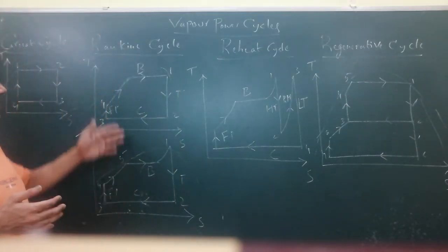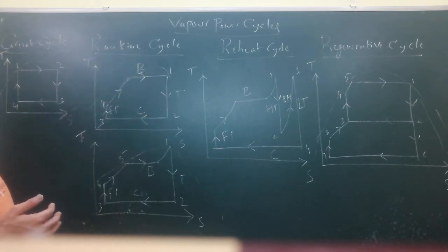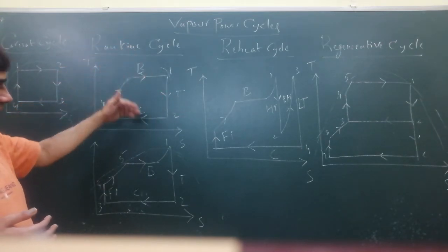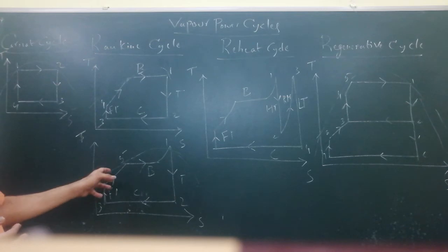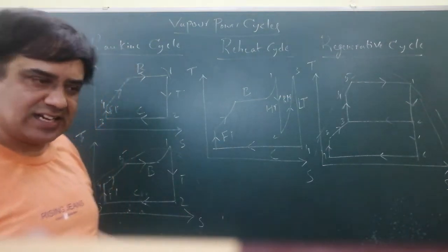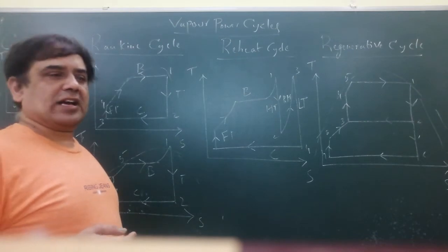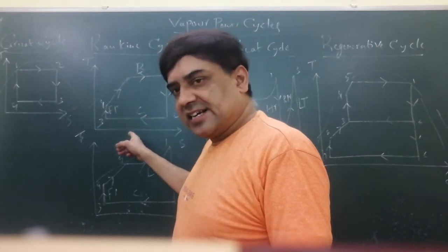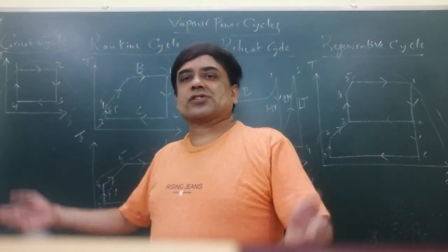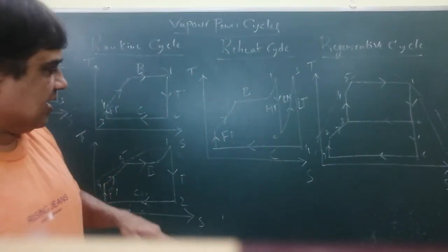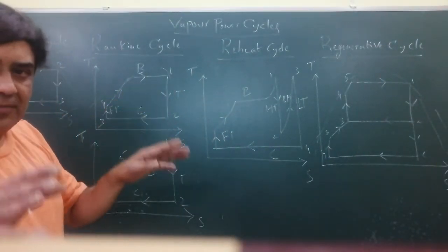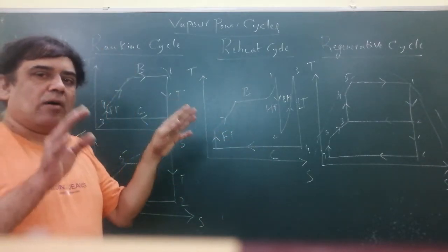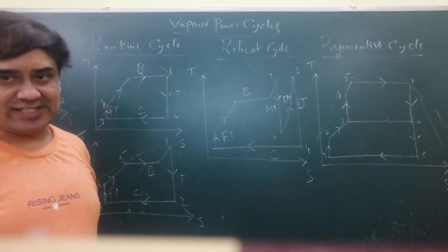Okay? Right. So this is the simple Rankine cycle where we find four components: feed pump, boiler, steam turbine, condenser. But below that, we have some sort of modification. There is not much change. Sometimes in any numerical problem solving on the Rankine cycle, boiler pressure and condenser pressure shall be given. We will be asked to solve for cycle thermal efficiency. In the second variety of problem on the Rankine cycle, the modified Rankine cycle, we find boiler pressure along with superheated temperature.